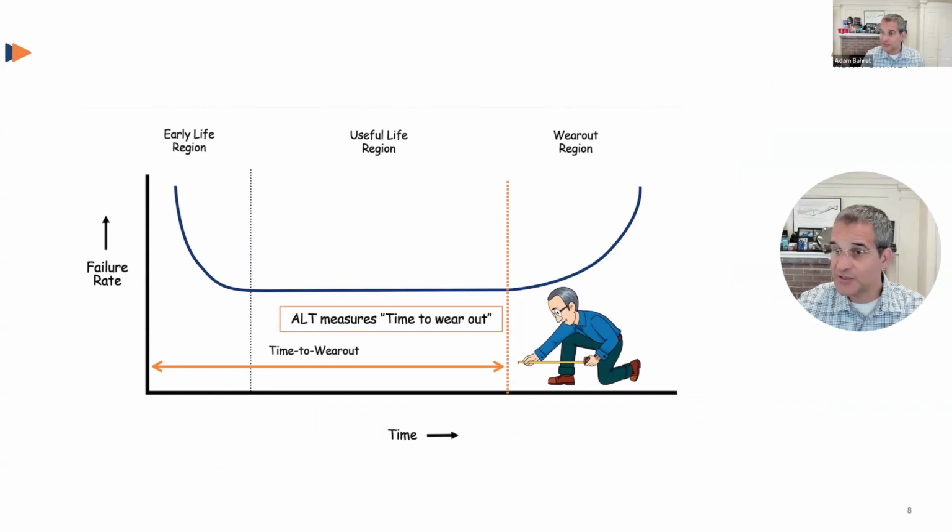Yeah, that's a great question. Of course, there can be different types of wear out failure modes that can occur, right? For that tire example I gave, one is the tire tread wearing down. Another could be dry rot, where the tire, just from UV exposure and ozone, begins to break down and crack. Those two would experience different wear out failure modes from different use cases, right?